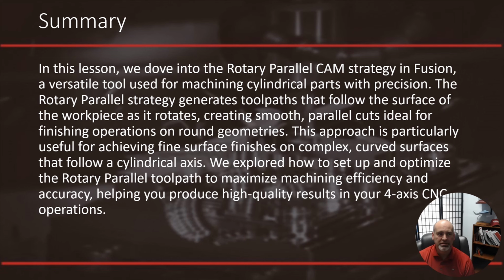Just in summary, in this lesson we dove into the Rotary Parallel CAM strategy in Fusion, and it's a versatile tool used for machining cylindrical parts with precision. The Rotary Parallel strategy generates toolpaths that follow the surface of the workpiece as it rotates, creating smooth, parallel cuts ideal for finishing operations on round geometries. This approach is particularly useful for achieving fine surface finishes on complex curved surfaces that follow a cylindrical axis.